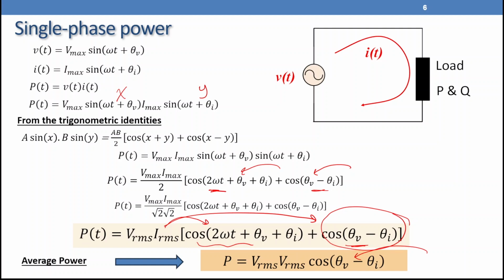But what we notice here, the second comment, is that the single phase power is not a constant function of time and is shifted by a DC level or DC component. And this is what we have as average value. Still we have a function of time. Can the three-phase power solve this problem?